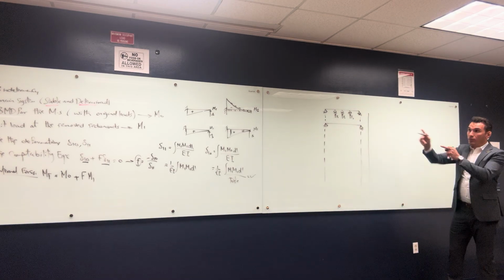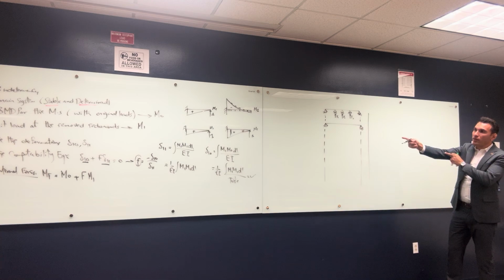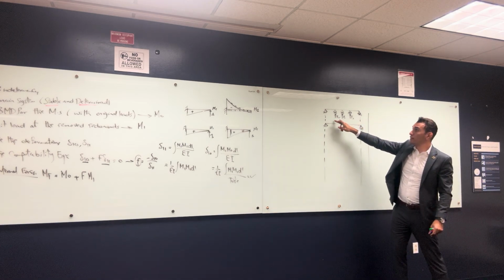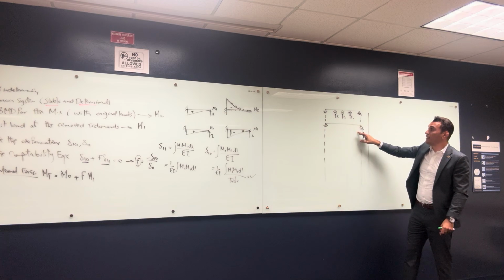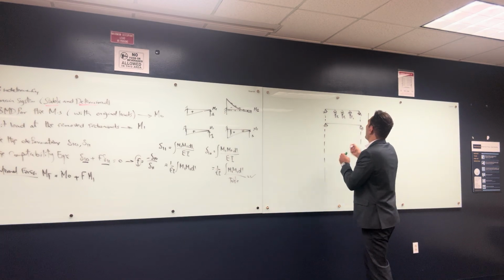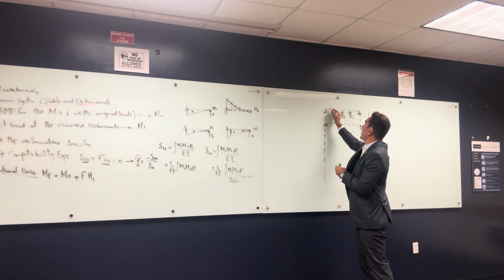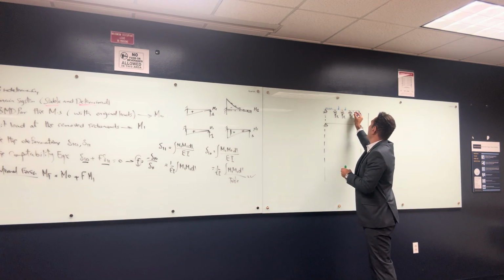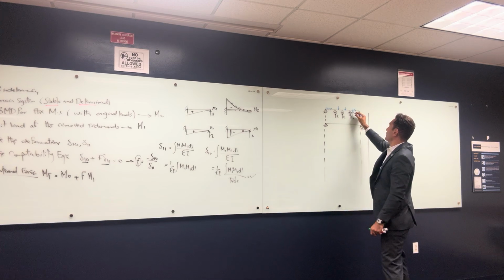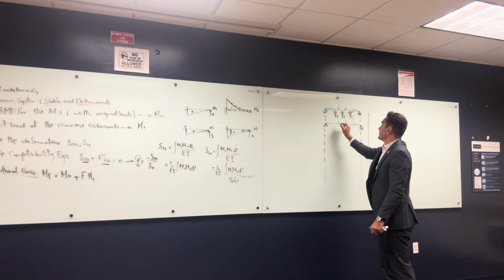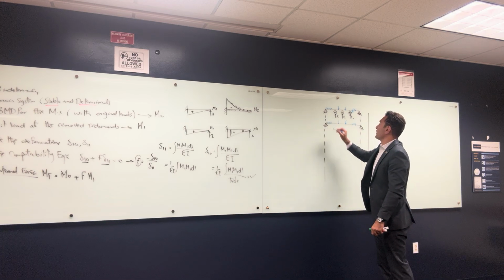Okay, so I'm using the flexibility method, or the method of consistent deformation, to find these 3 reactions. I decided the redundants, then I choose the main system, which is determinate and stable. Let's say this system has a general load: a distributed load here, then a concentrated load here, and maybe a concentrated moment here, okay? So I put all the original loads in the same locations, same everything.